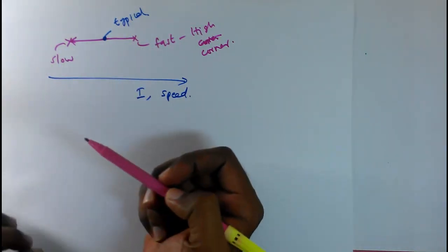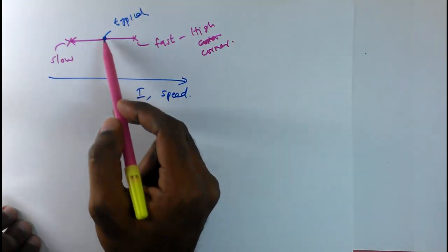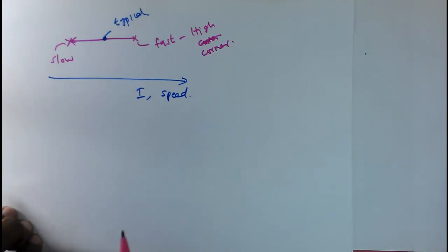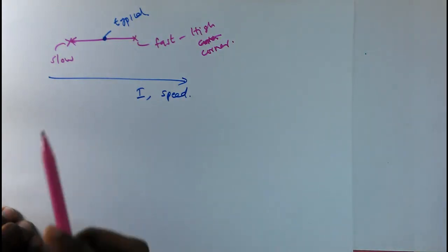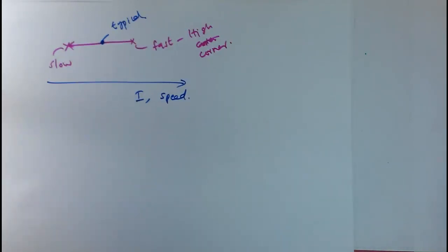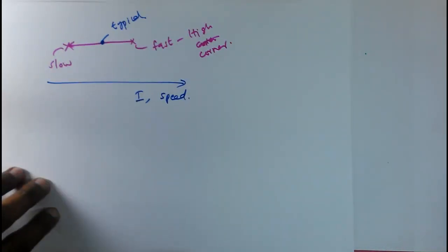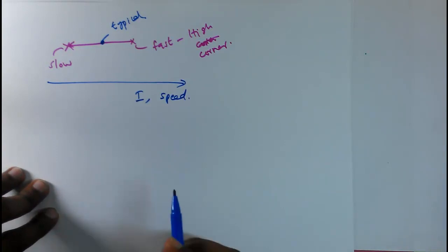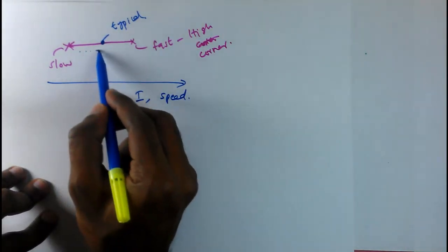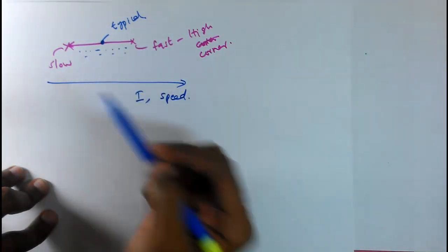So you cannot exactly say that your MOSFET will always be in typical. So when you design a circuit involving the MOSFET, you should ensure that your circuit is robust to process variation. Its threshold voltage can vary, the current through the MOSFET can vary, and the speed of the MOSFET can also vary. So your MOSFET will be anywhere in between these values.